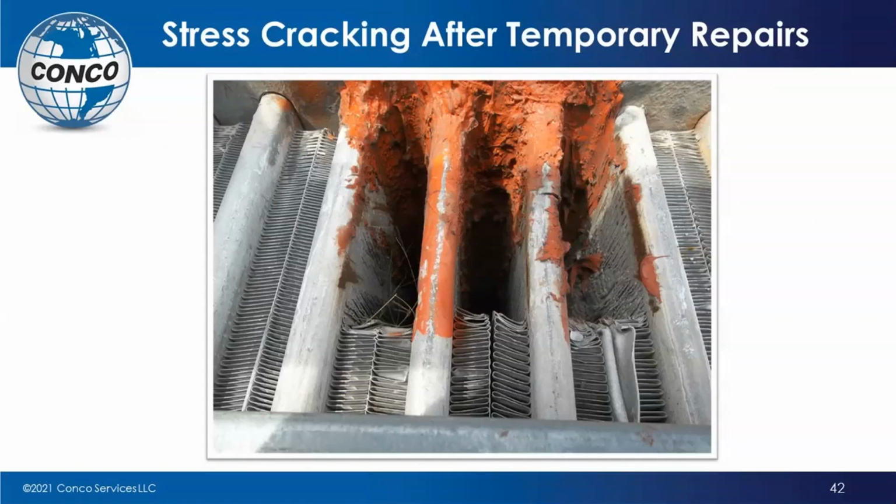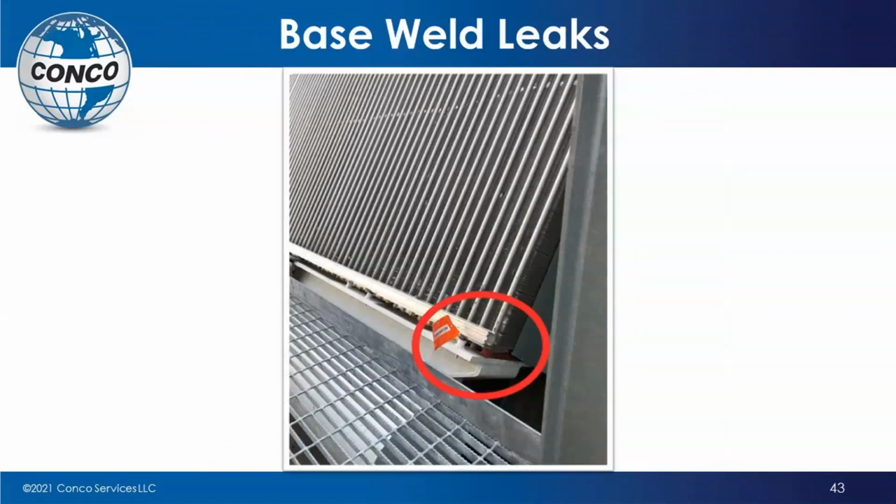So you've just moved that stress point up. Now over time, between the steam going down and the heat and the cooling of the air itself, that takes a lot of pressure, with cracks. So anytime we're out looking at a unit, we take a look at where things have been repaired and we inspect that area, because in many cases, there's going to be another leak.